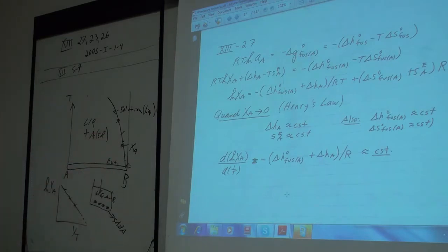But first of all, you have to measure the composition very accurately. The other problem is that, even with salt and water, but especially in a metal or a salt at high temperature, these particles don't stay down at the bottom nicely behaved. They can stir up in the liquid and you get tiny particles of solid in the liquid. When you take your sample, you're always gathering up some of the solid, and then you almost always analyze it as too much A.